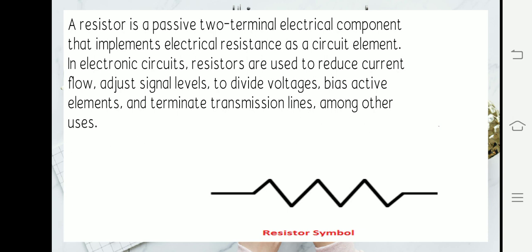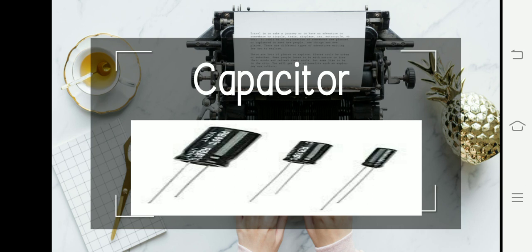If a component in your circuit requires less voltage than the rest of your circuit, a resistor will create a voltage drop to ensure the component does not receive too much voltage. The resistor will create a voltage drop by slowing down or resisting the electrons as they try to flow through the resistor. If a component receives too much voltage, it may be damaged or not function properly.